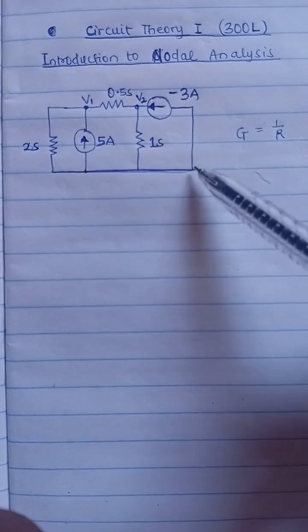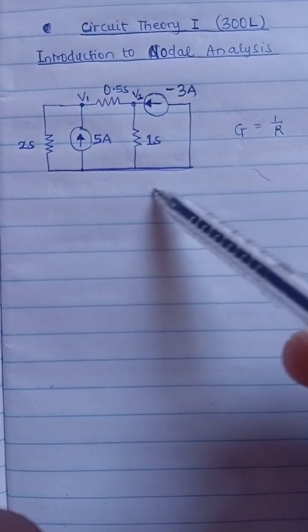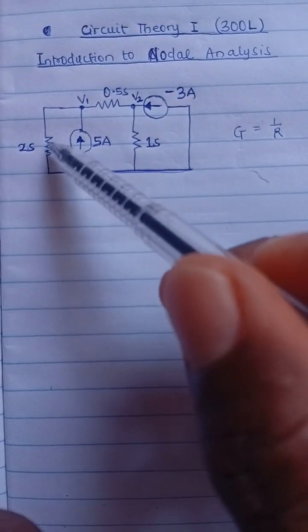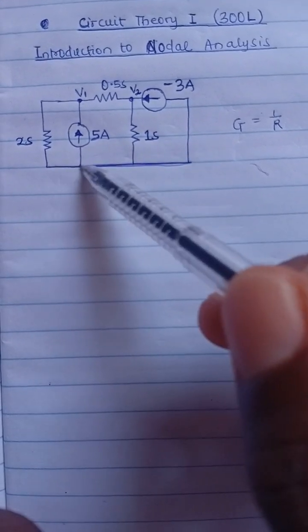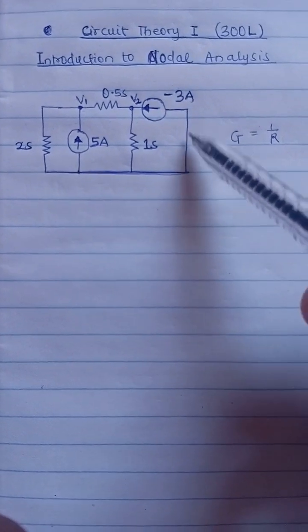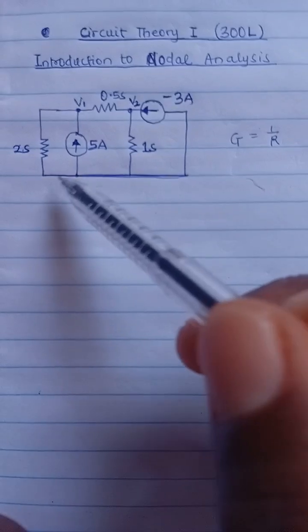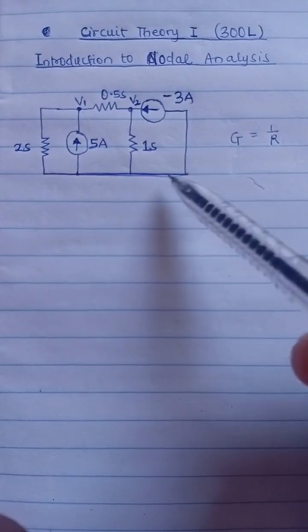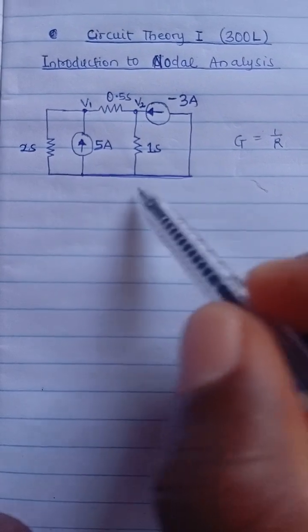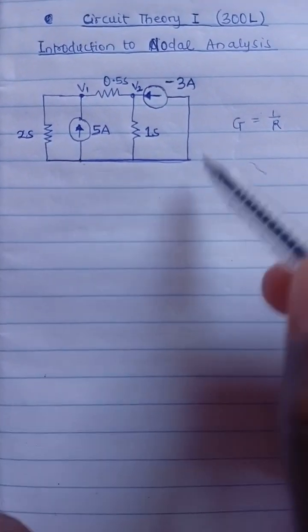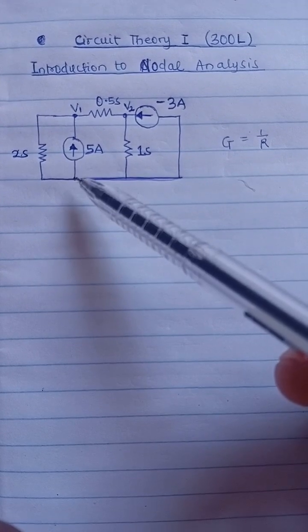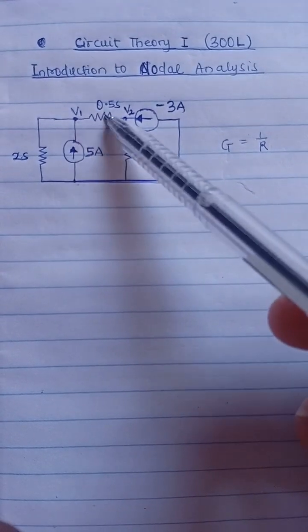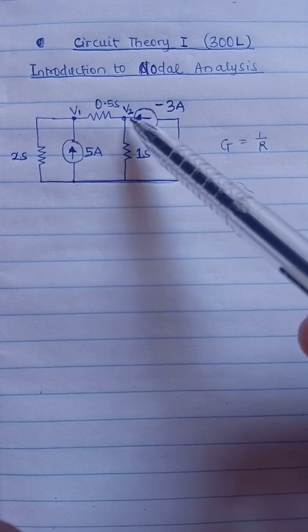But if you take the whole of this lower part of the circuit together, because this resistor joins here, the current source joins here, and the resistor joins, this is just like a bar or a conductor that joins all of them. So if you take all of them together, you can consider them to be a node. So this is also a node. However, this very node is called a reference or ground node. It's called a reference node because it has more elements connected to it. For instance, this node here has 1, 2, 3 elements connected to it.